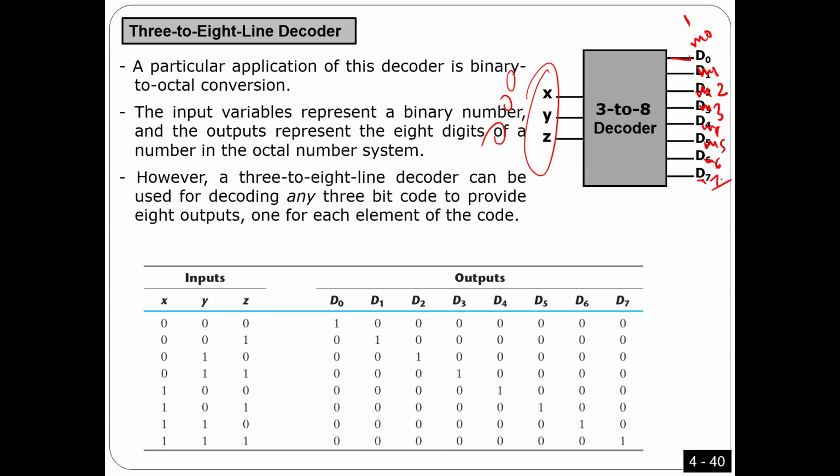Now I will explain. If you have a decoder, again, this is not the only way to use a decoder. A decoder can be used for other things, for selection, similar to the last example I explained, where the decoder selects one of 4. But anyway, one way to use the decoder is to implement any function. Why? Simply, as I explained in chapter 2, any function is the summation of minterms. Minterm 0 or minterm 1 and so on.